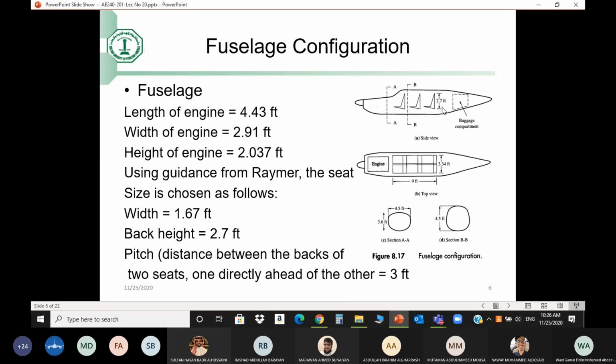Finally, before I see if you have questions, the last thing that will need room inside the fuselage is the baggage. Remember, we had like 120 pounds of baggage. So if I can convert this into volume, how big would you put 120 pounds of baggage? Again, that's common sense. 120 pounds, about 60 kilograms. You can say I have 3 large pieces of luggage or 4 medium pieces. So how big are these going to be? Will they fit in the tail cone of the aircraft?